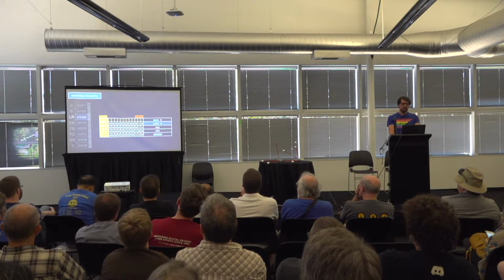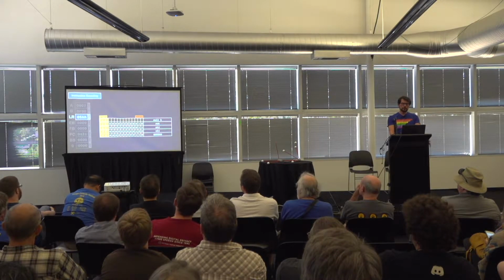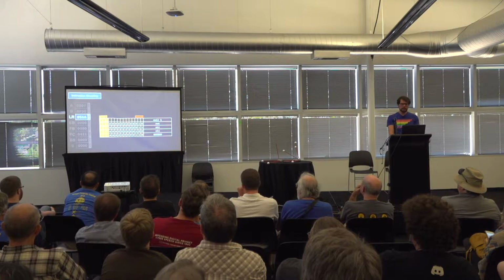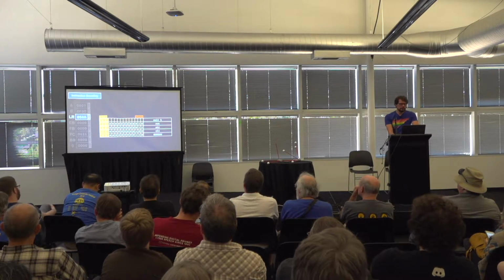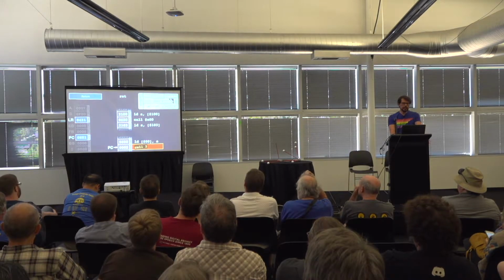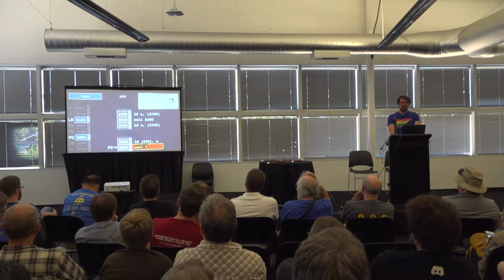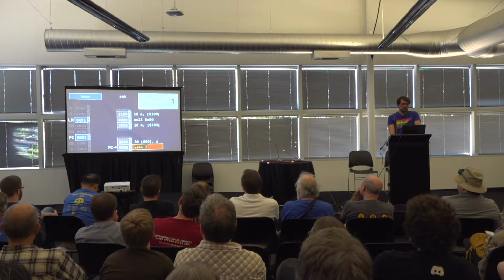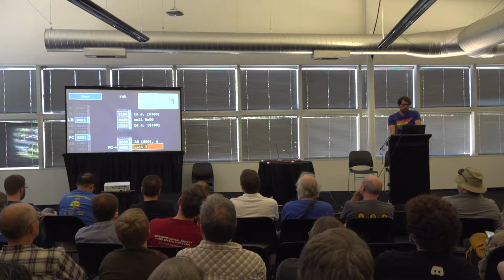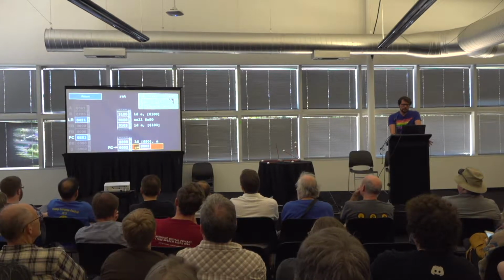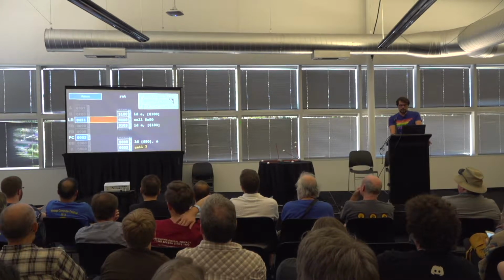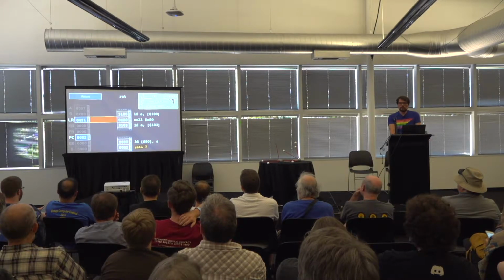There's one more special call instruction called to LR, the link register, which is the return instruction. But this one is not a special case. Instead, return is a side effect of calling memory location 2. Call 2 will continue execution at location 2 in RAM. Location 2 is the same as the link register, in this case 0421, representing the return address.